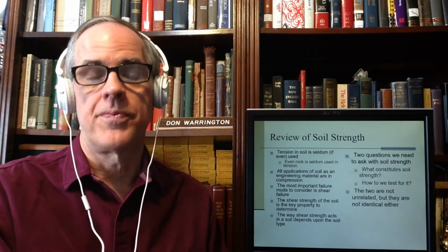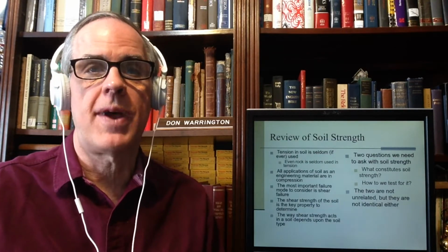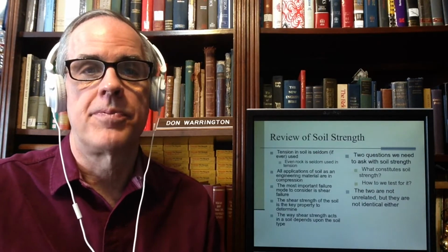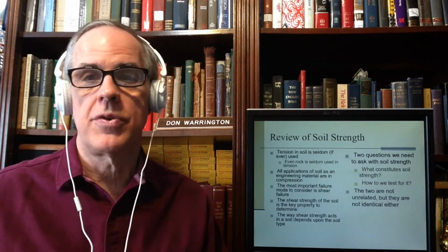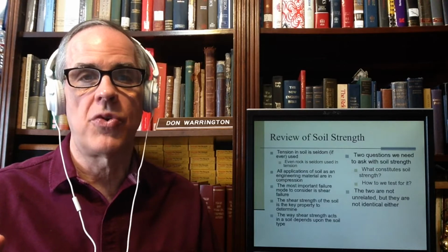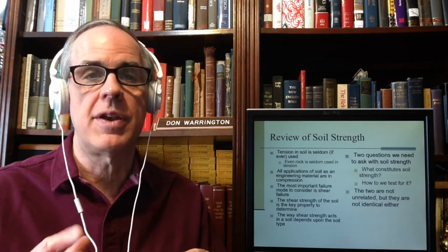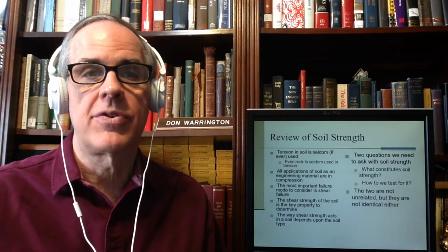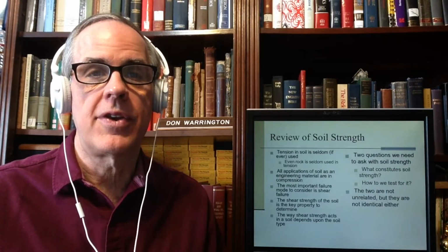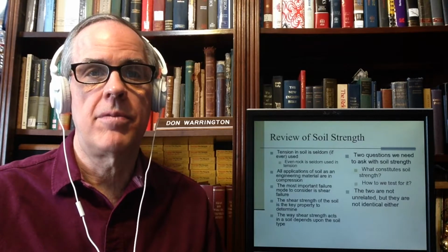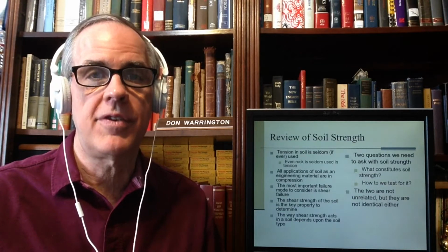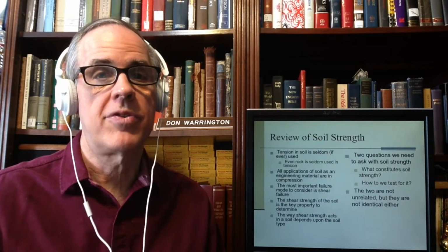There are others too. For example, a few years back we had a professor at UTC who had a method where you could actually put a soil into a machine, and using lasers, it would tell you its angularity and particle size, which is a major advance from the sieve analysis, although you won't necessarily get the same result.